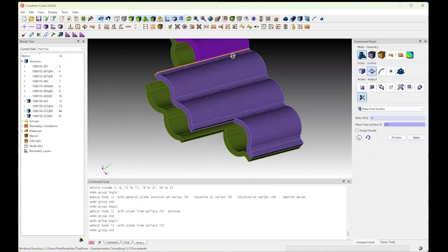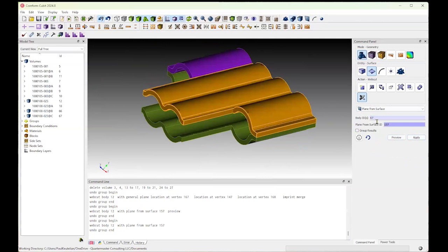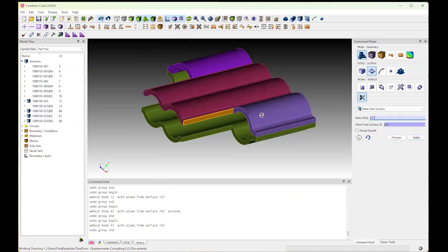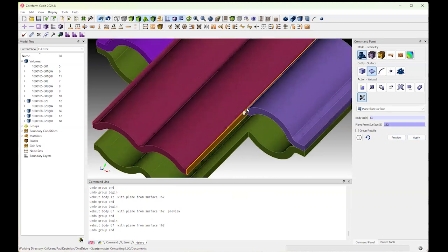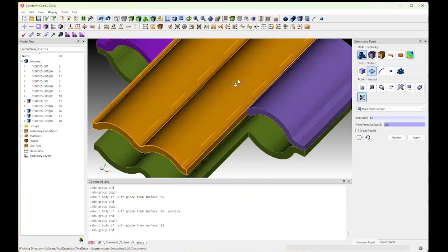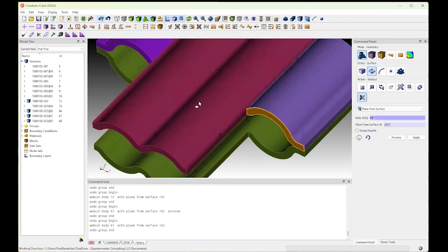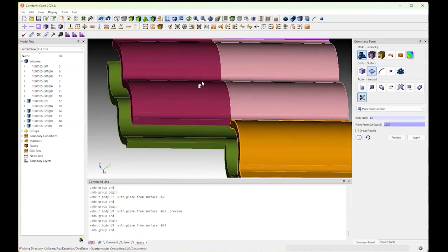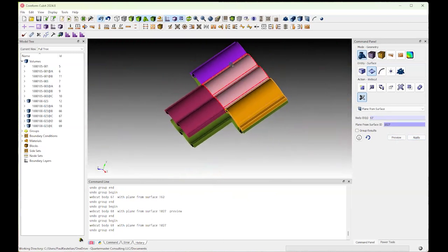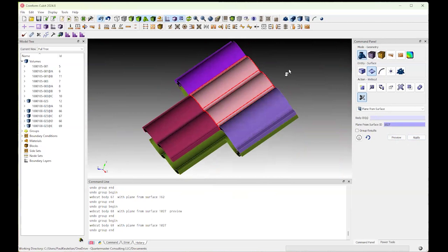As you can see, I'm also cutting away at some of these wings here so that I can create rectangular pieces. And those have been a bit easier to mesh for me. And then here too, in this corner, this discontinuity, I'm going to want nodes at these specific positions too. So again, I'm going to make one more cut right here just so that the meshes between these volumes line up.